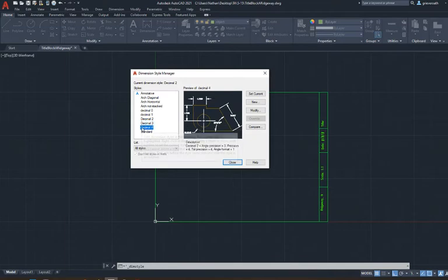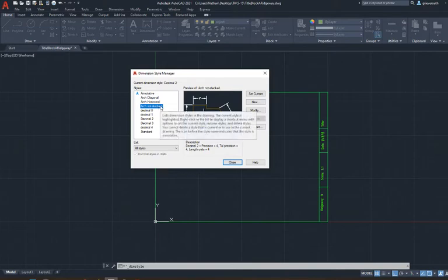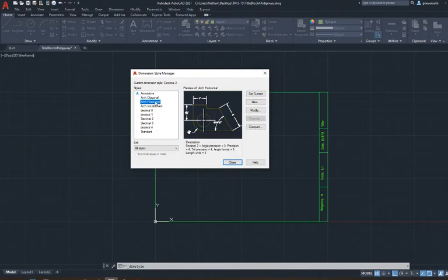Decimal 4, etc. Now for architectural, that 1.25 line will be interpreted as an architectural line, therefore a measurement. Architectural specifically is using the imperial measurement system. So that is a measurement in feet, inches, miles, that sort of thing. So in architectural, that line would be shown as 1 and 1/4. This is because the architectural settings are for fractions.